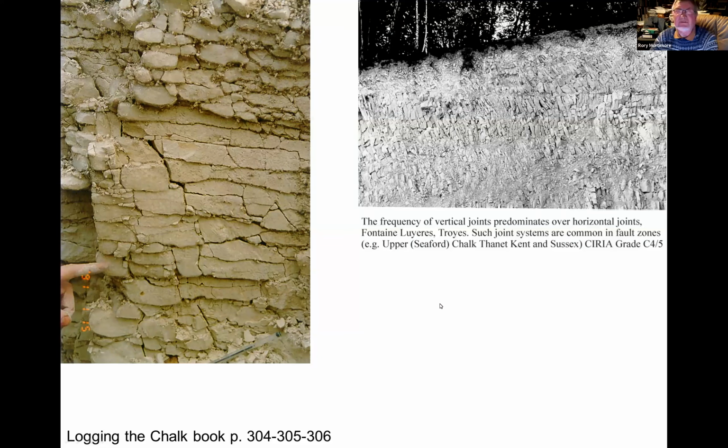So we'll start, first of all, looking at the near ground surface and the weathering of the chalk. And here we have two different fracture patterns, one from a trial pit. This happens to be on the A27 Brighton bypass during construction, but this trial pit shows a typical ground profile from near the top surface, near the soil horizon at the top, coming down through the chalk, and you can see you've got horizontal fractures closely spaced, and they're open. And towards the top, you might notice, those of you who've got good eyesight, unlike me, if you look at the date, it's January 1991, and there's ice around every block.